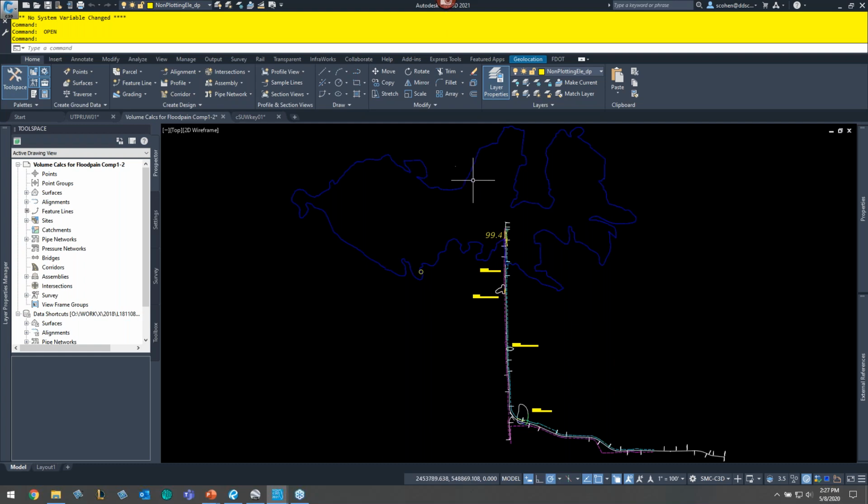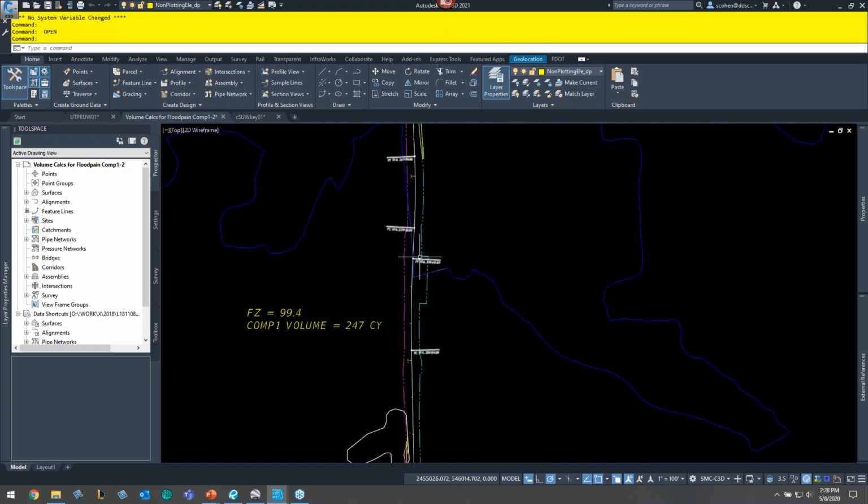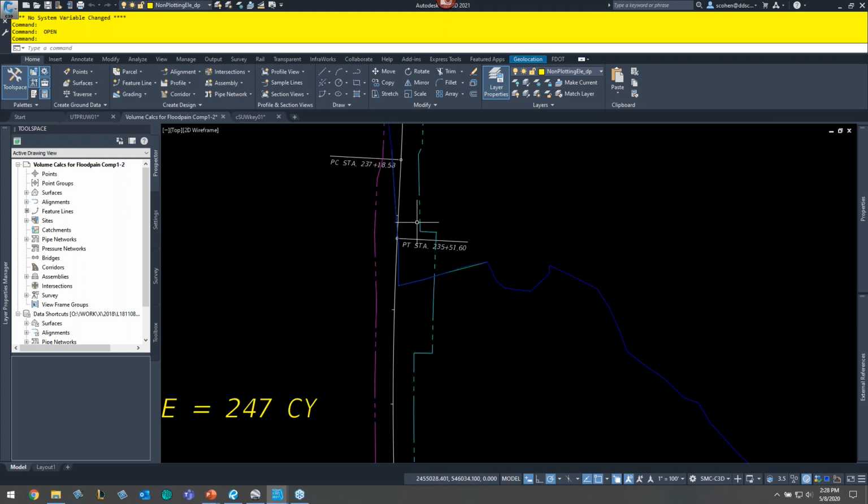Okay, so that's why this is a pretty critical thing you have to do, because if you need a floodplain compensation pond, you may have to get right-of-way. And here's the thing: your pond has to be touching some area where this floodplain actually is. You can see right here, for this project, we're actually acquiring a little bit of right-of-way because we needed a floodplain compensation pond. Turns out we were actually inside the floodplain, below that elevation, and we were filling.